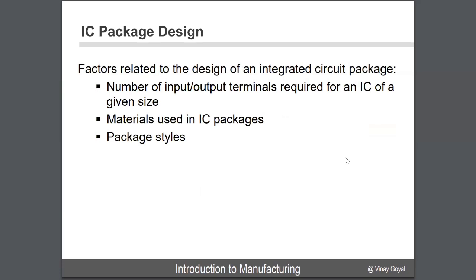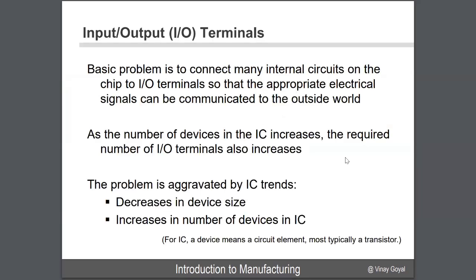So what are the factors that drive the package design? It's really the number of input and output terminals required for the integrated circuit, the materials used, and package styles. For the input and output terminals, the basic issue is how you can create the appropriate electrical signals and how you're going to connect them to the outside. As the number of integrated circuits increases, you also need to increase the number of input and output terminals. The problem has also been aggravated over time because the sizes of these chips have decreased.